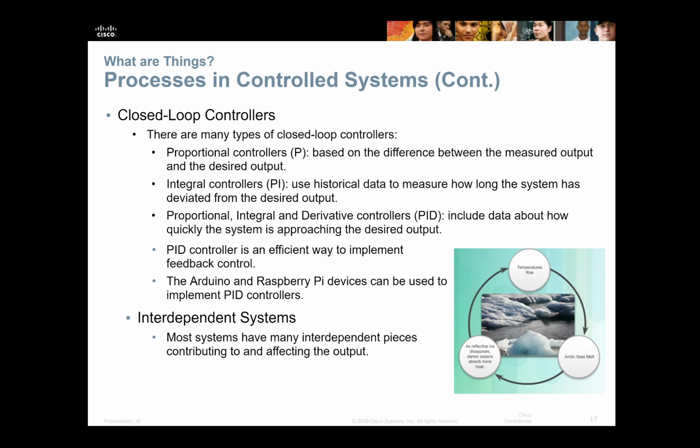So it has the proportional part, but also the integral part, which uses the historical data, meaning if you are just approaching the set value slowly, the integral of that offset is growing, and then if you use that in addition to proportional, then basically you reach this set point faster.